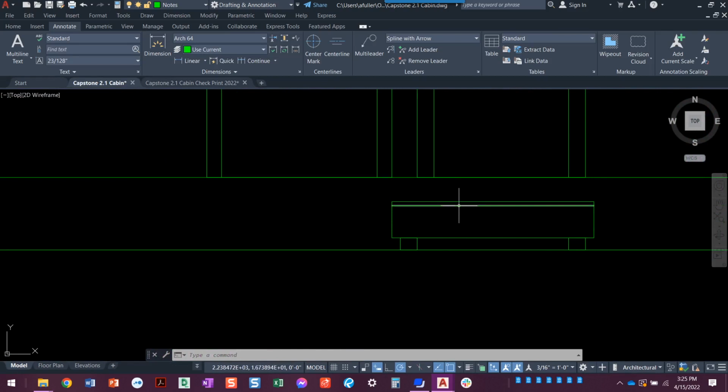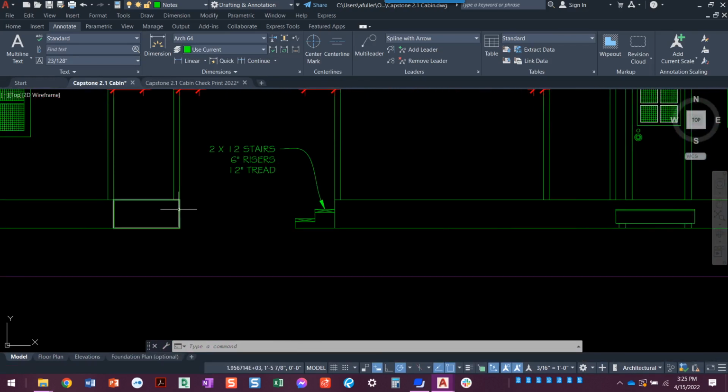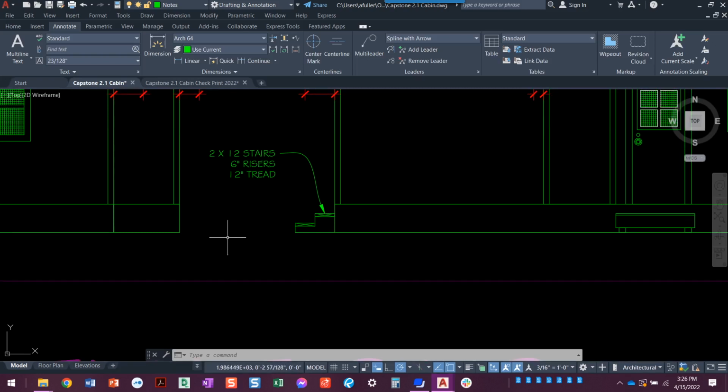We already talked about how to do it over here on this view of the side deck. So we would just have it coming, remember it's a 6-inch step down, and then it's the 5/4 inch decking, so you can just offset by 1 inch, 5/4 by 6-inch decking, and then it had the 8-inch joist, and then the 4x4 post at the bottom. So I will trust that you can do that, but don't forget it. You definitely want to have that done.